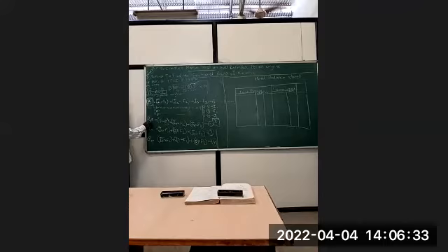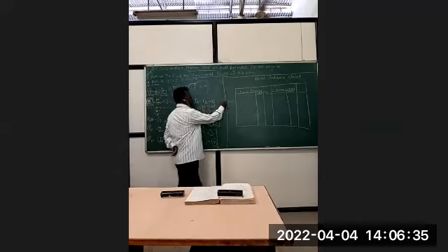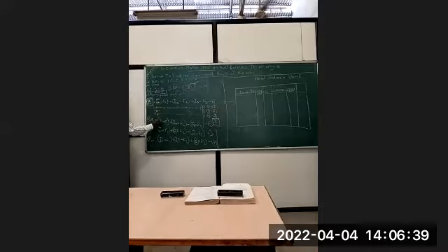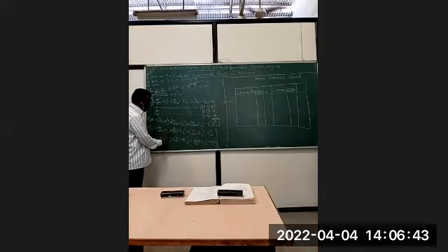So every time we have to ensure that this particular speed of 2000 is being maintained irrespective of whichever cylinder is cut, because we want the frictional power to remain the same.